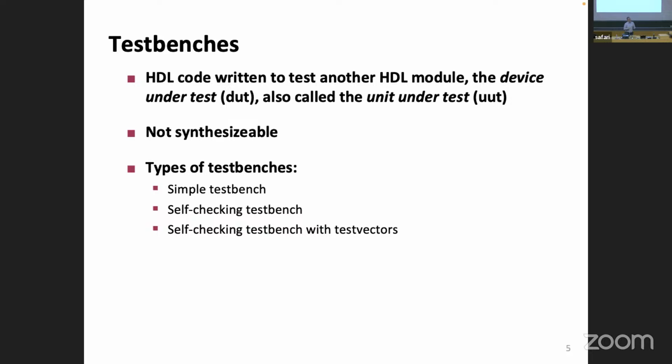This is important, and you will see a lot of constructs where you say, why don't I use this in circuit design? Well, the language is the same. It's still Verilog, but part of it is synthesizable, meaning that it can be turned into a circuit. And part of it is just for simulation purposes, modeling purposes, and those are not synthesizable. We will start with the simplest thing, then we will continue making it a little bit more interesting, and finally, we will come to the self-checking test bench with test vectors, which essentially will boil down to this thing here.